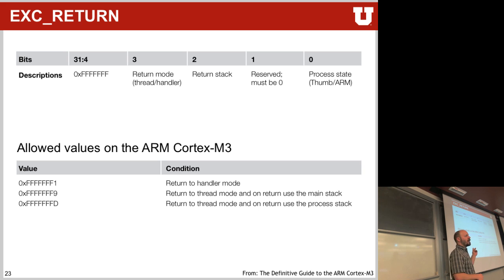Behind the stack pointer that we have, there are actually 2 shadowed stack pointers in the background, and you can switch between them by using these functions. So far we always have used the main stack because that's the easier one to use. But you have a process stack that you can use if you have applications.